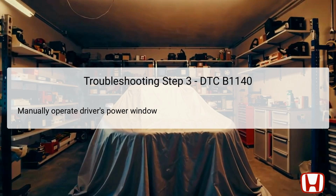For instance, if the window doesn't move at all, it might indicate a physical blockage, motor failure, or other mechanical faults. This hands-on testing will provide you clarity on whether the initial diagnosis of DTC B1140 holds true based on the window's physical operation. After performing this step, it will be necessary to check for DTCs again to assess any changes presented by the system.